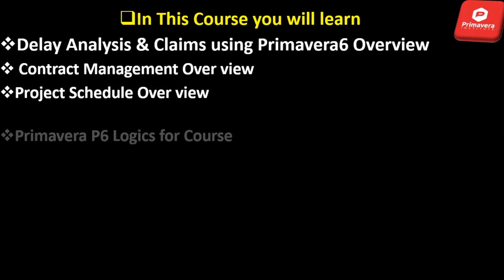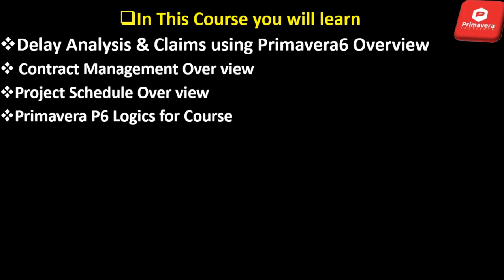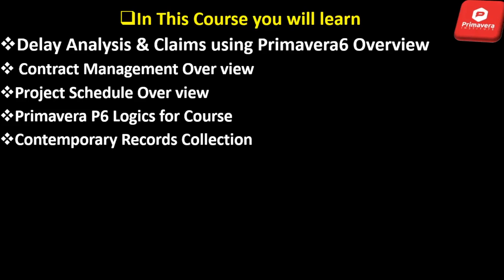After that you have to become familiar with Primavera 6 logics for this course, how you have to incorporate all the delay events and what the logics are using Primavera 6. Then in the execution phase, if some delay happens, there is the contemporary records collection procedure. You have to study all those things in detail.